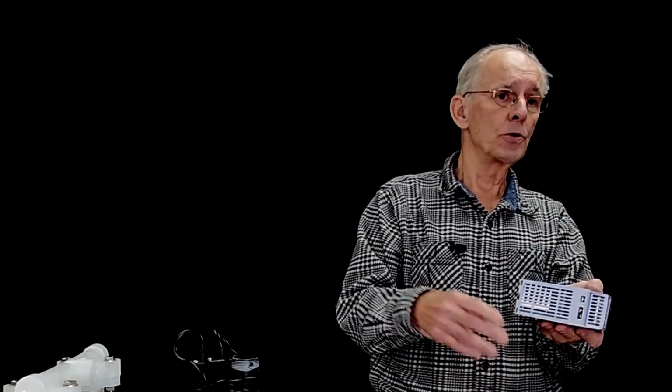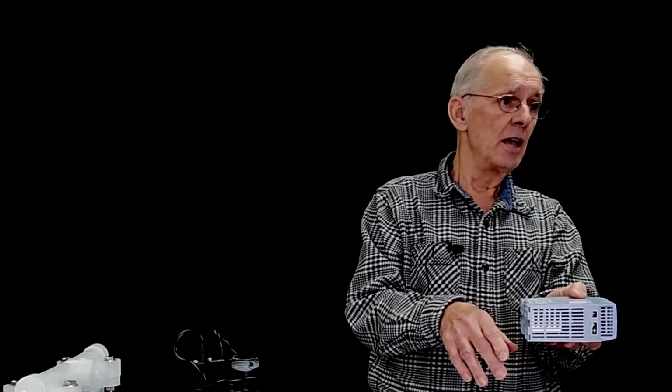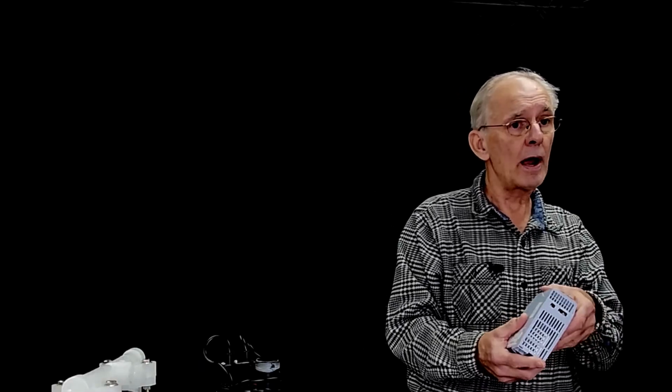Centrifugal pumps also have slip. In other words, the water isn't always positively propelled by the impeller, but you can compensate for that. If you want to hold a certain amount of pressure, you may actually be having a very small flow, but you're running the pump much faster, so you get the pressure. So the combination of VFDs and other variable type drives give you a very wide range of flows and pressures out of a single pump. So that's the basics of pumps.